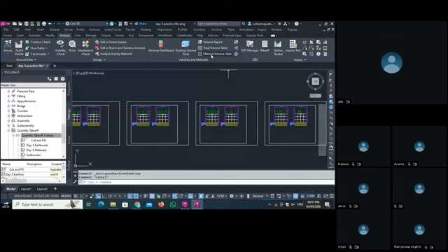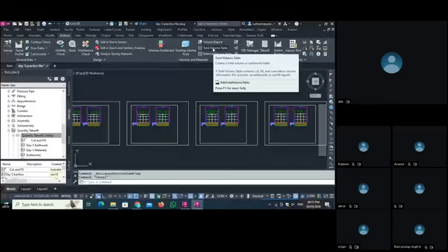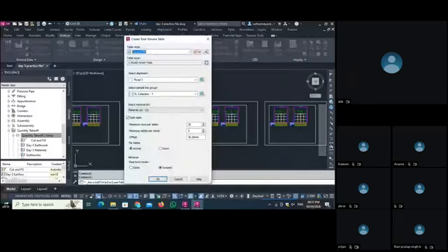Here we have a volume table, the total volume table. If I want to create a volume table, I can select the volume table. As I select it, you can see the cut and fill table style. A layer is there. Our road 1 is selected, our sample line is selected, and the material list. Let's select material list 2, then we select material list 1 also.